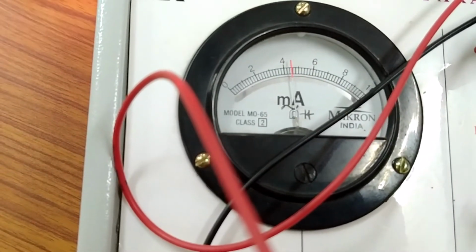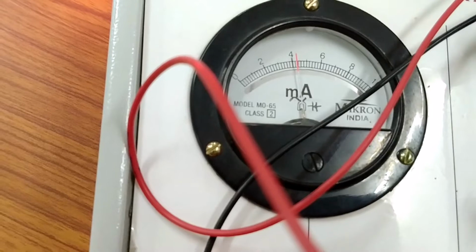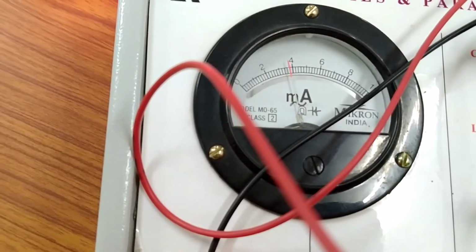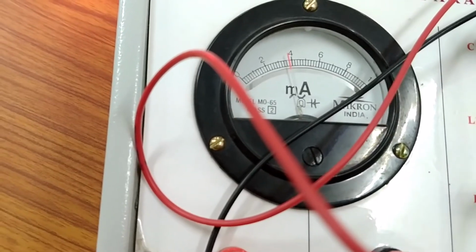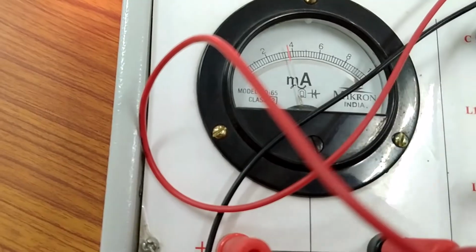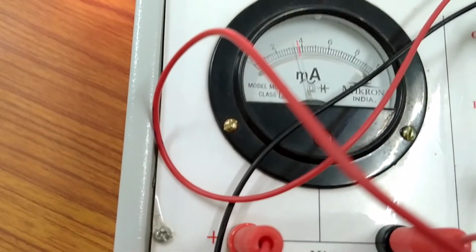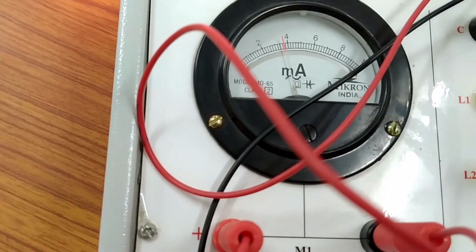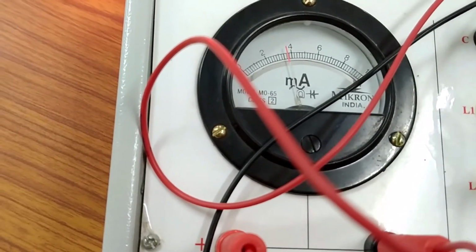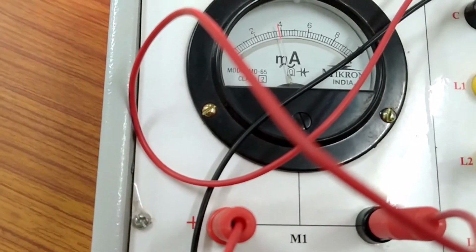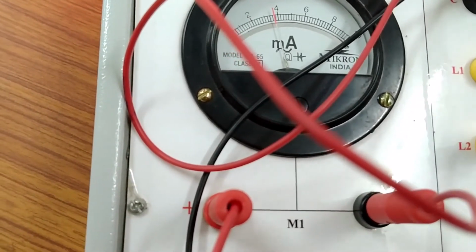So you take different values until the current increases with frequency to the maximum. If you take a set of readings, maybe 6 readings while going up to the maximum, and 6 more readings while coming down, then you can draw a graph, and from the maximum value in the graph you can find the resonant value.